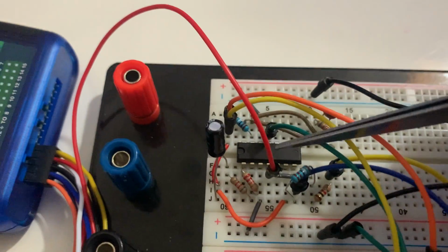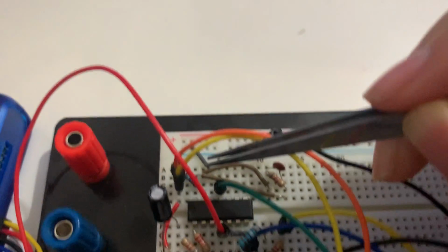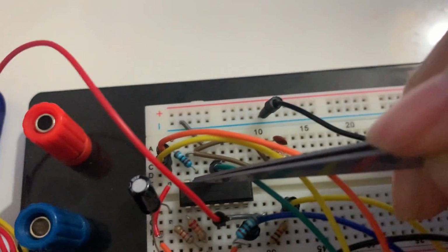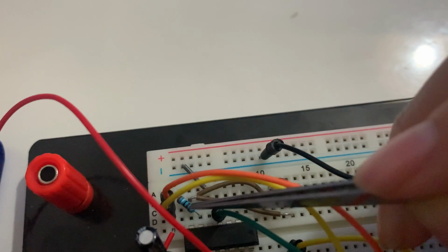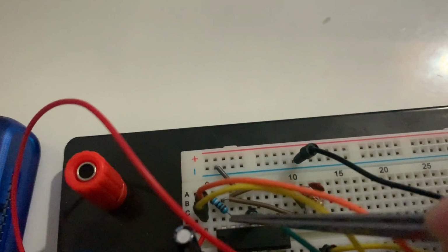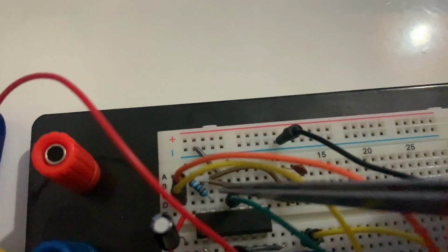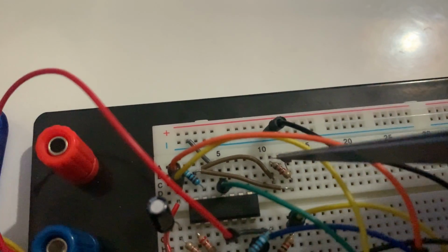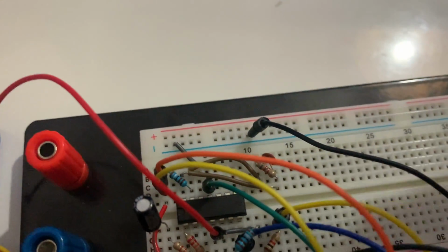So first, this is VCC, this is V ground. This part is the low pass filter. So as you can see, the negative input is connected with this 3.9 kilo resistor, and the resistor is connected to the signal input, and the positive input here is connected to the ground, and also the output is connected with a resistor and a capacitor in parallel, then connected back to the negative input. So this forms the low pass filter.